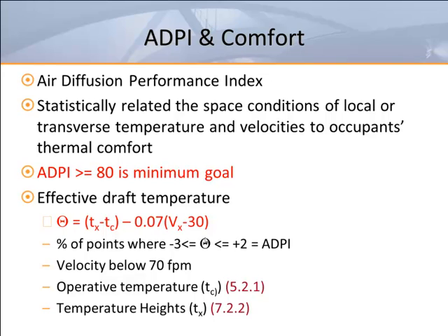The test, which is described in the appendix of ASHRAE Standard 113, prescribes taking a comprehensive survey of locations in the occupied zone at 4 specific heights. 4 inches above the floor, or ankle level. 24 inches above the floor, or waist level for a seated occupant. 43 inches above the floor, or neck level of a seated occupant.